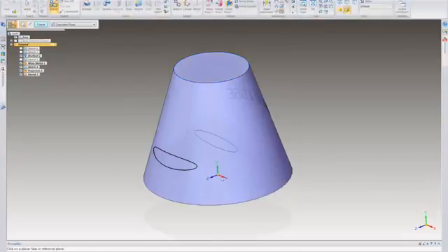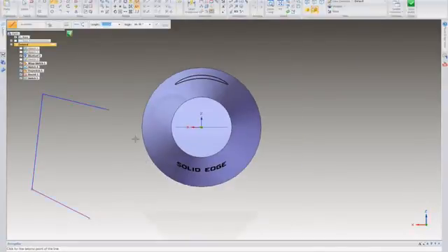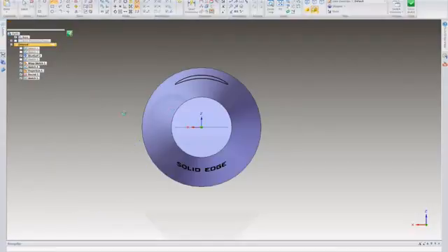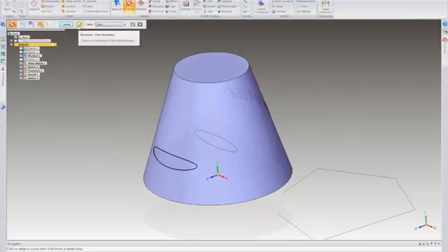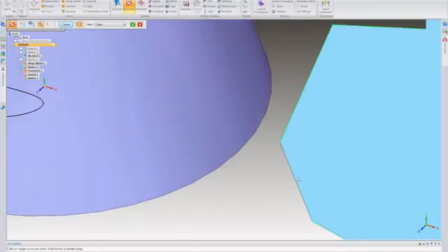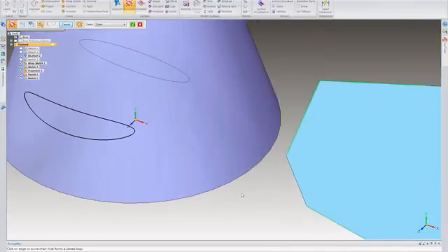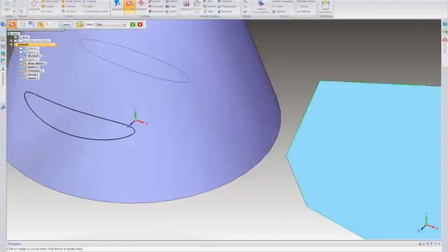If I have a sketch that is open, I can use bound. And you'll notice, without actually having to worry about that end being sealed off, it will go ahead and close that off for me now. Before, you'd always have to have a complete enclosed boundary to do that, and that is new for ST6, whether it's open or closed. So you can toggle it. Obviously, you see it fails if I have it set to open. Of course, if I come over here and close it, it immediately just caps that off for me.